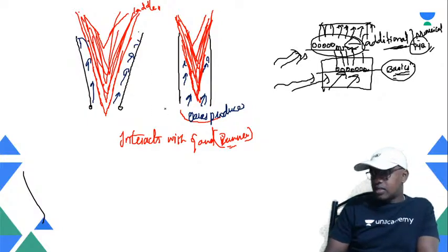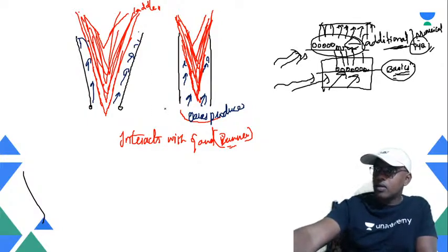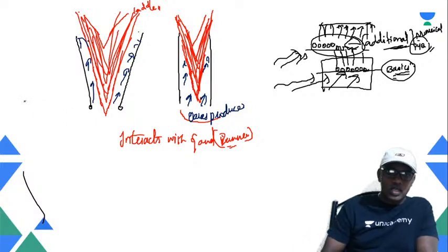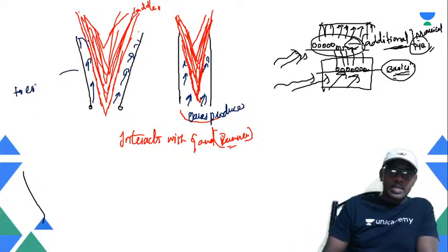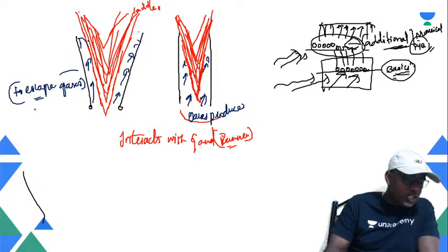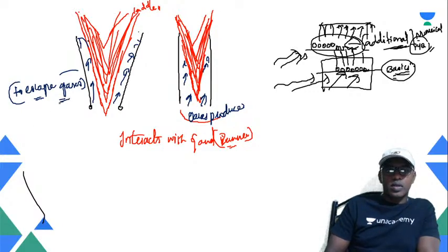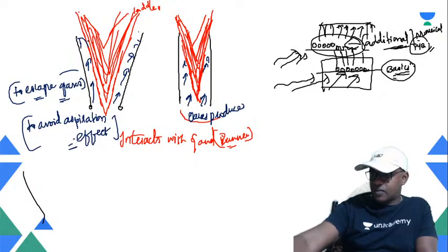So these are the reasons, my dear people, the sprue is made with a tapered cross section. So what is the benefit? To escape the gas, to avoid the aspiration effect. Correct? We have to use the correct perfect lines. These are the simplest ones. Thank you so much, Shubham Kumar sir. Fantastic of you. To escape the gases so that it can avoid the aspiration effect as well. Hope it is loud and clear to you all.